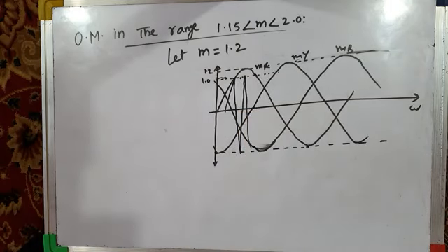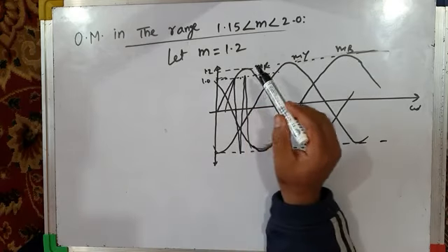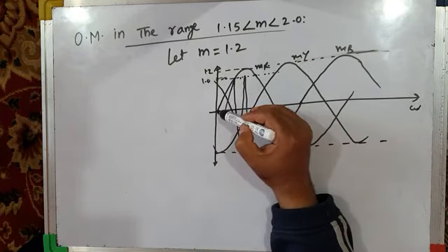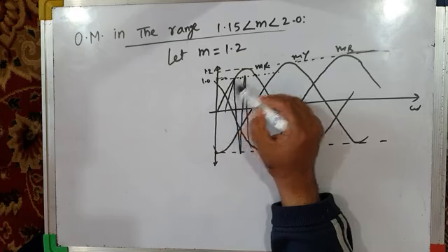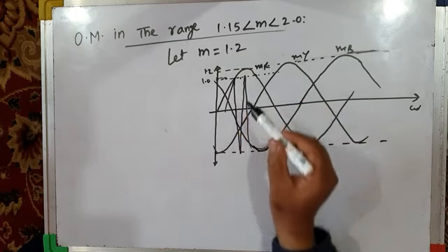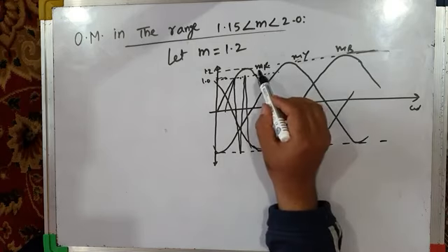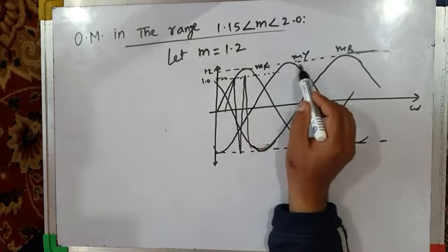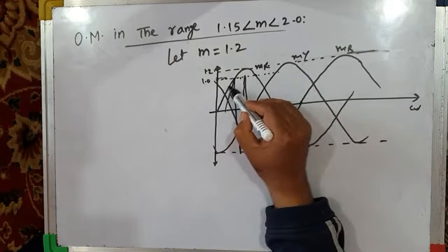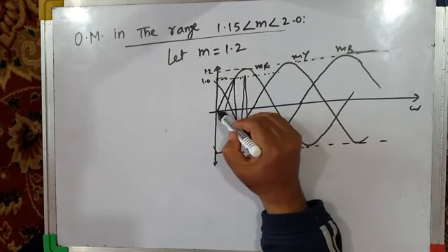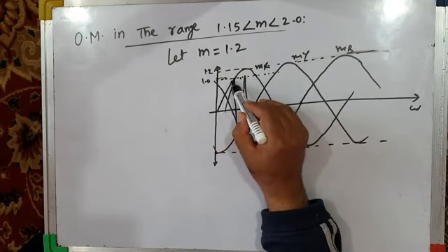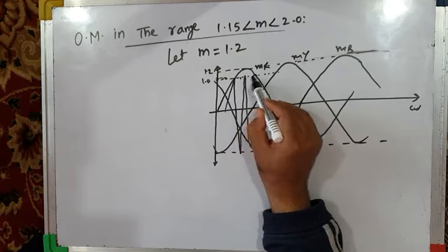Okay, so for example, the instantaneous average pole voltage VR will increase in the same manner as MR, because I have told you that average pole voltages are scaled versions of sinusoidal modulating waves. So from here to here, your average pole voltage VRO will increase in the same manner, but then here it will get clamped.